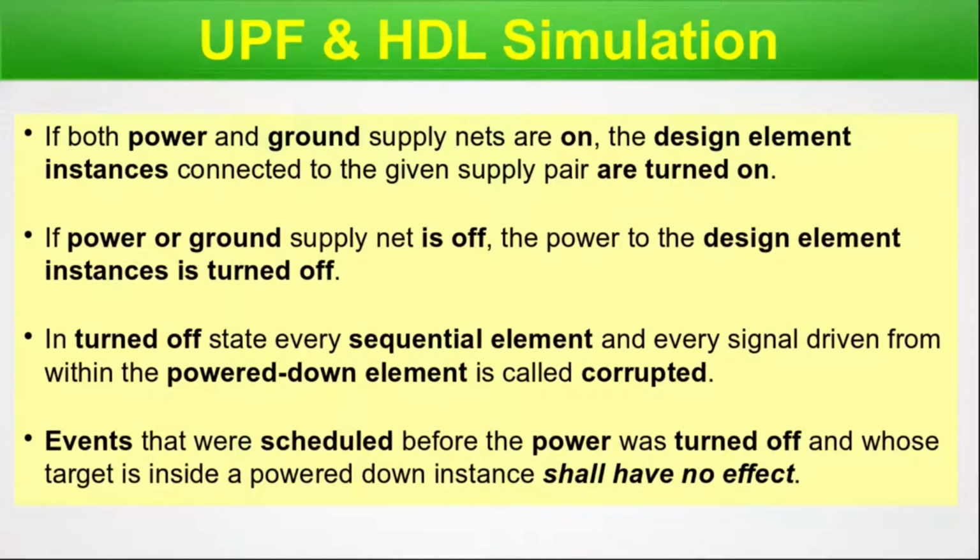Events that were scheduled before the power was turned off and whose target is inside a power down instance shall have no effect. So suppose there is a block which we have just powered down and some time ago we have started a vector from outside which will operate in time t after the power down sequence, so that will have no effect.